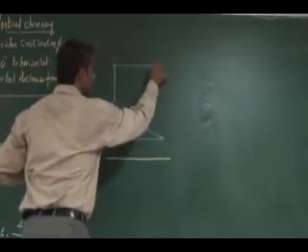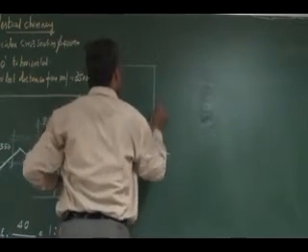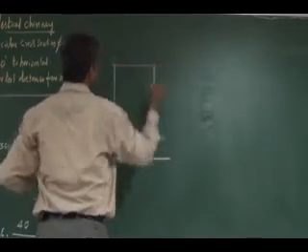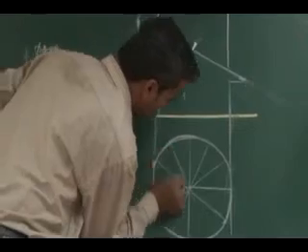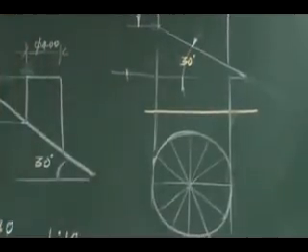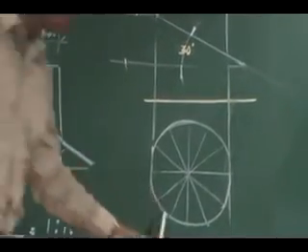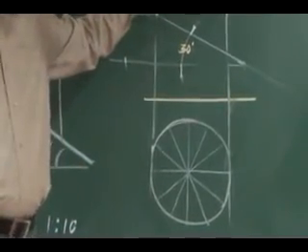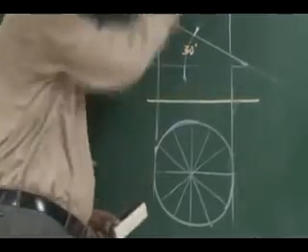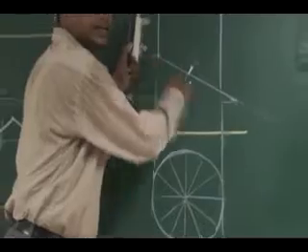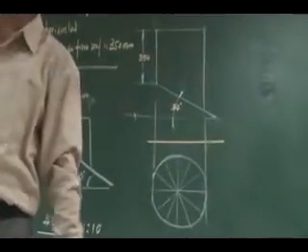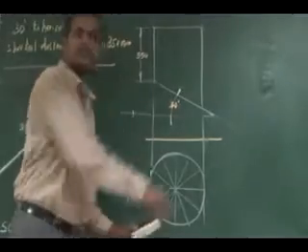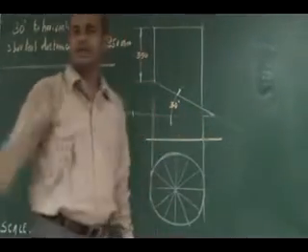Then I can close this to this slope. Divide it into 12 segments and notate them. Then you can project these points to your front view. You will have a base here. This will be something like a cutting plane, the 30 degree plane, which cuts the cylinder fully. It cuts all the 12 generators. You have to mark 12 cutting points.